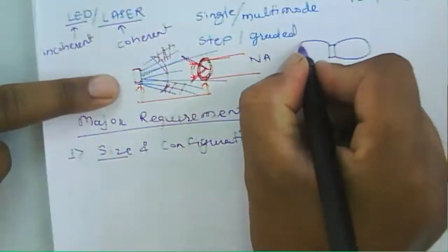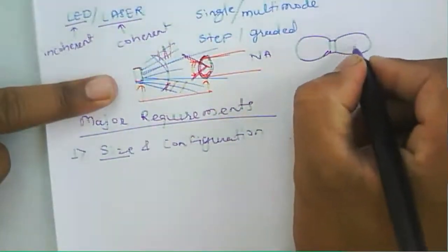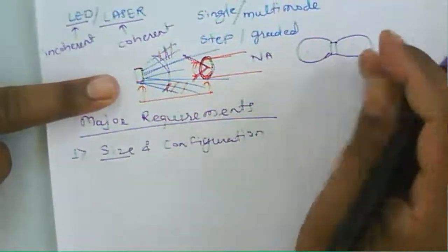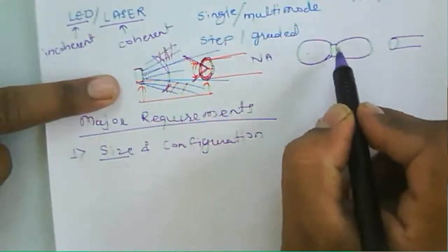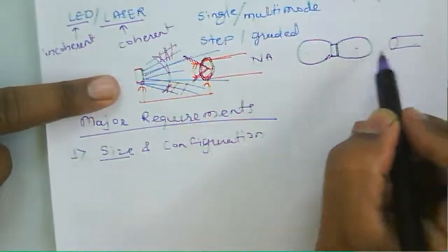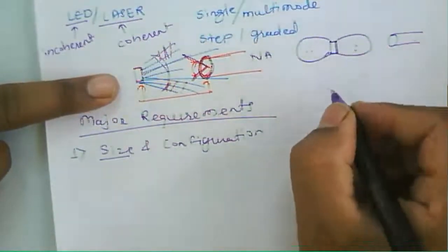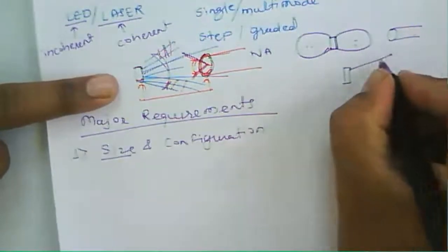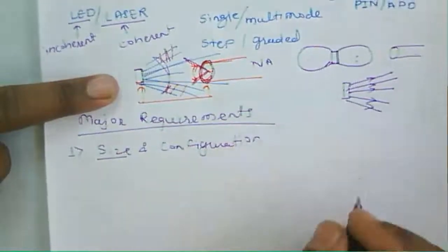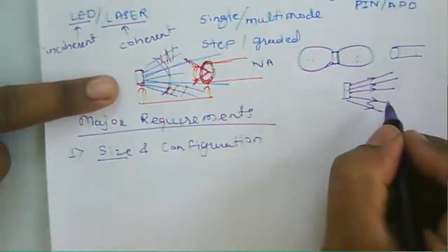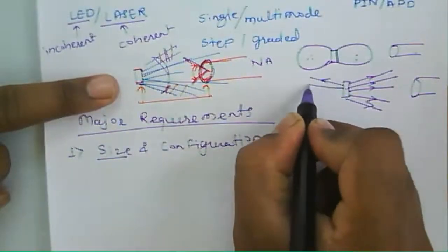But if you see that radiation pattern, this is about a bidirectional. In the case of this first lobe, another lobe here, only if we keep the fiber here, only this particular radiation emission from the source will be coupled to the fiber. So this other one will not couple. In general we say that a light emits, likewise this one is about a light emitted from the source in this direction. If it is unidirectional, then it will couple.